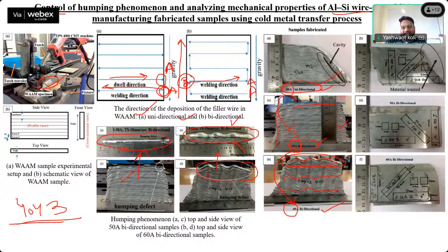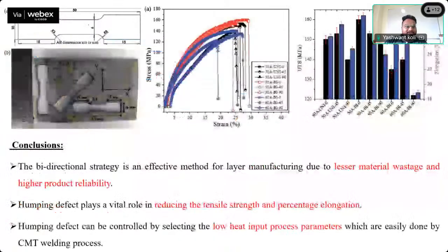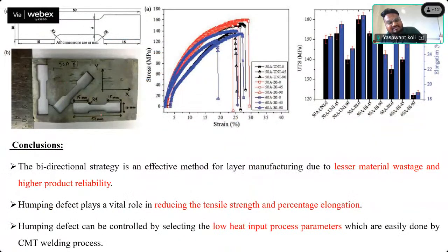And after this, this is the as-fabricated sample that we have got, and we have gone through the CNC milling process. You can see this surface is cleaned, and now we are extracting the sample. After extraction, what we did is calculate the tensile strength. So we extracted horizontal, vertical, and inclined samples, because the ASTM standard E8M we have followed. So we have got the stress strain diagram.